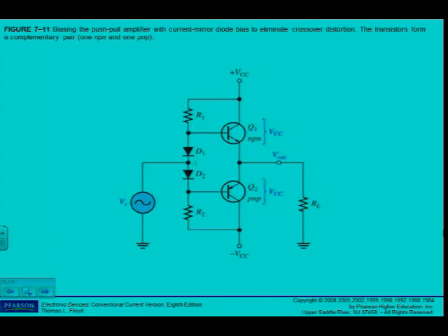There's the solution. Now what is this amplifier going to be called? First we started with the class B, and then the class B was only the positive alternation. Then we did the push-pull, positive and the negative alternation. Now what are we going to call this one? When we did biasing, what was that amplifier called? A class what? Class A. So I did the biasing, it was a class A. So what do you think?